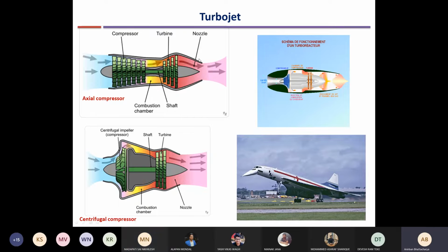Anyway, so for most aircraft applications, the nozzles are convergent in nature. Okay, so the combustion products go out either at sonic velocity, means in choked condition, we will discuss this later, or at subsonic velocity. Remember, sonic velocity can change. Means speed of sound depends on temperature.